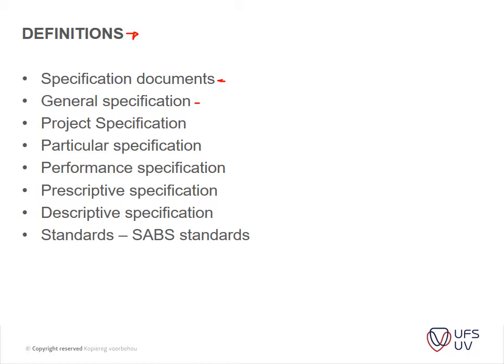What is a set of concrete test cubes? Is it only one test cube done, or is it a set of 3 cubes done? Whereas one is tested usually on 7 days, the other one on 21 days, and then a third one is left as a supplementary test if any of the first 2 fails. Okay, then you've got your project specification.